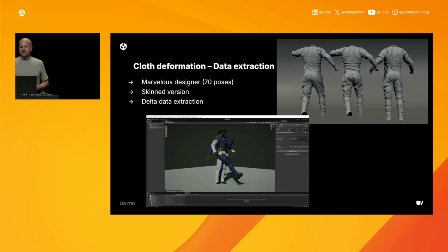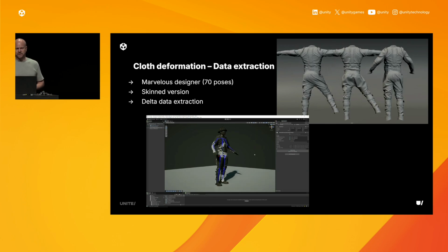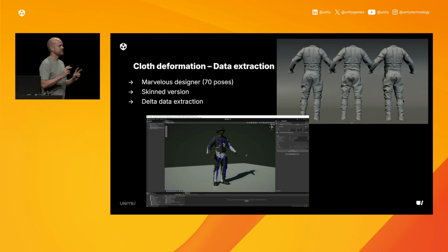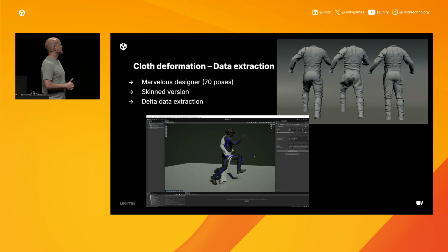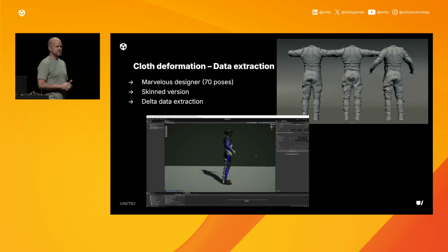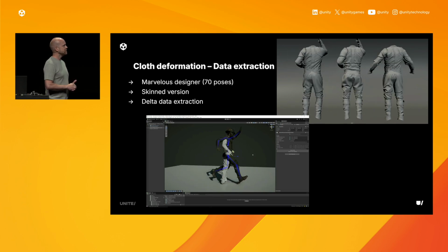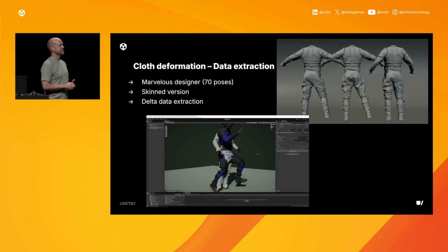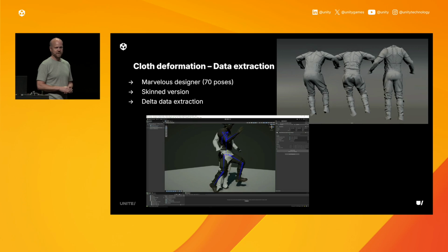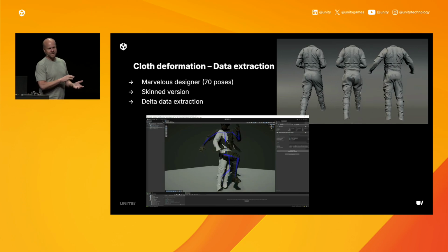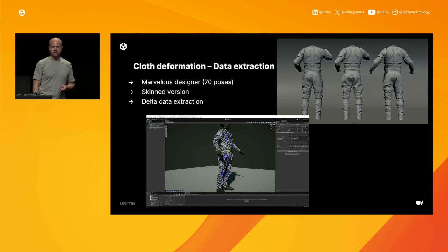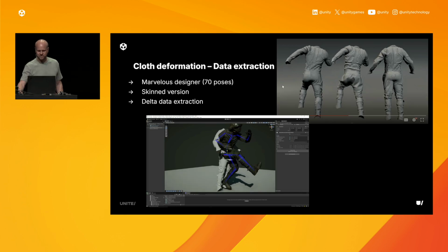With that delta data extracted, we bring it into Unity, where we do the final extraction process. We take 17 joint rotation, or quaternion, values, and then we play back the delta vertex values at the same time. That gets fed into the model to train it, and it takes about an hour. Then you drag and drop that model and look at the results.